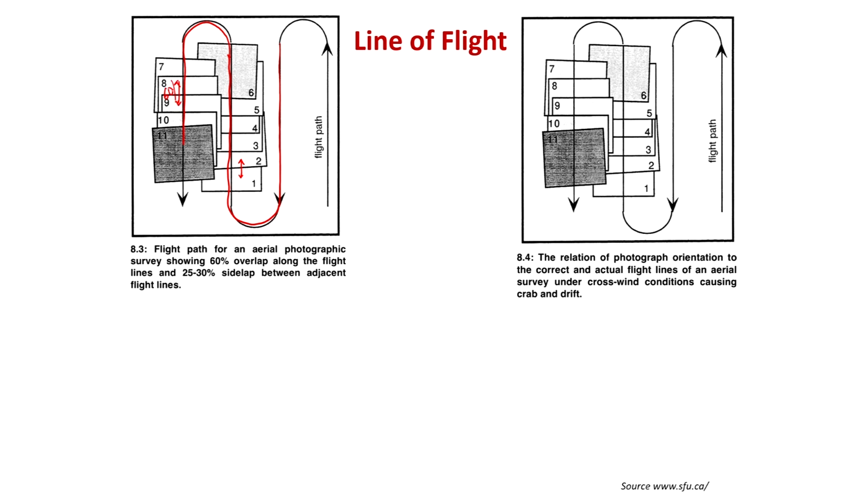This is your 60%. This is your 60%. Whereas this one will have your overlap of 25 to 30%. So even in this, you can have an overlap of 70% also. Okay, but anyway, that depends on what criteria, but minimum at least you should have 60% overlap.